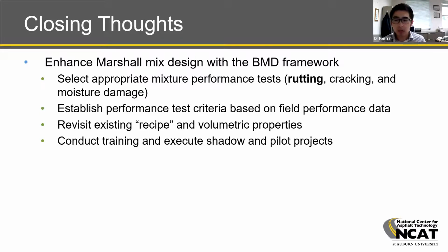Then we need to select those tests and criteria based on field performance data. Then we do some shadow projects and look at how this specification works. Then we go back to revisit some of the existing recipe or volumetric parameters we have. Eventually we want to rely on performance requirements instead of volumetric requirements, because that can give us better control of the mix quality.